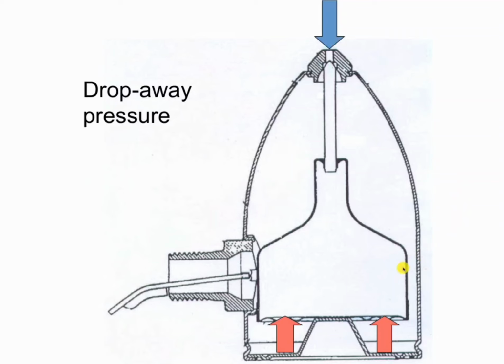And let me just briefly reference the whole thing with the commercial boilers. A cast iron residential boiler, you can set that. And I'm talking about one that heats maybe between a 1 to 3 family house or brownstone or townhouse or multiple dwelling, whatever you're dealing with. 1 to 3 families, let's just give that a rough estimate. You would typically find them running at about 2 to 2.5, 3 psi. You can set those boilers a lot lower.